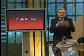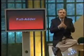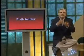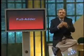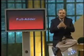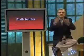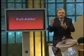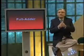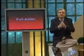For the input combination 0, 0, 1, the sum output is 1. For the input combination 0, 1, 0, the sum output is again a 1. The input combination 0, 1, 1, the sum output is 0, the carry output is 1. The input combination 1, 0, 0, the sum output is 1, carry output is 0. Similarly, for the input combination 1, 0, 1, the sum output is 0, the carry out output is 1.